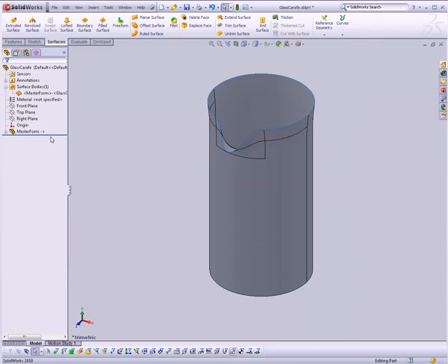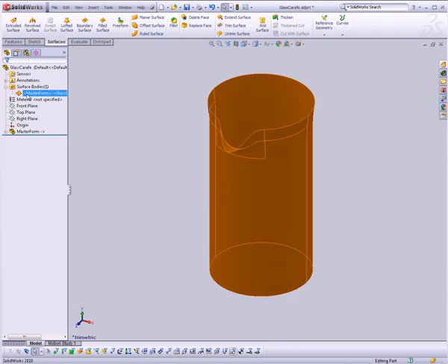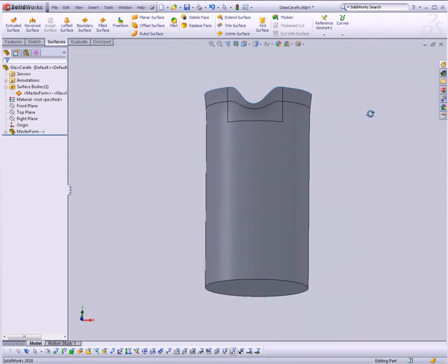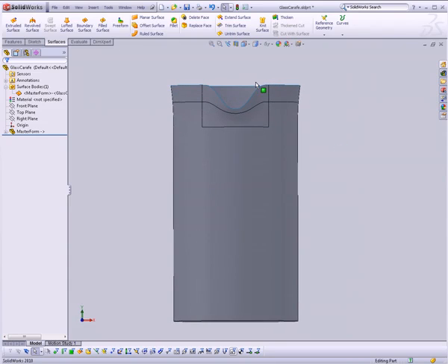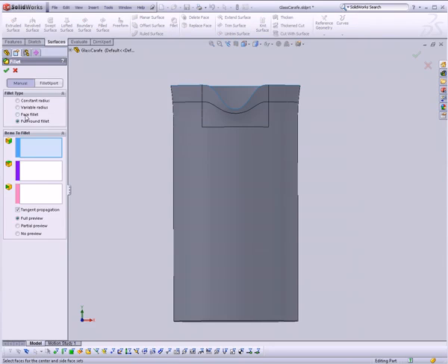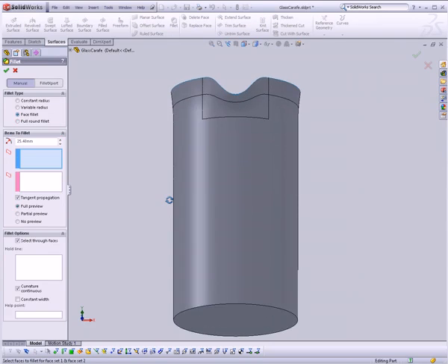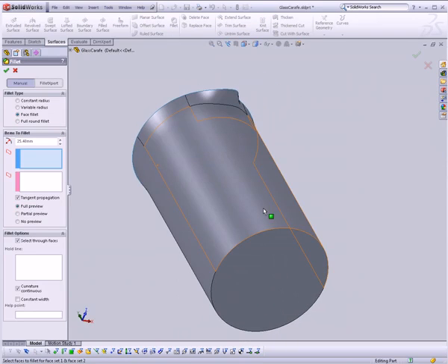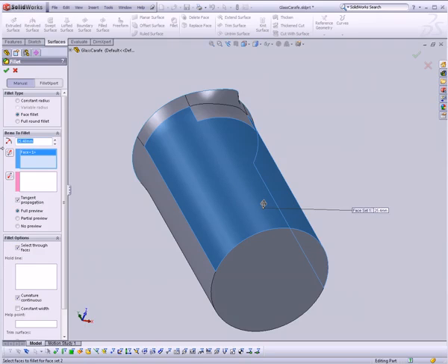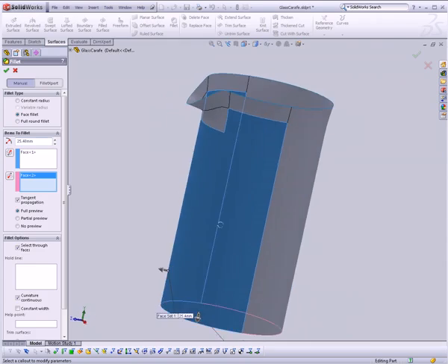So now you can see we've imported our master form and we have that surface that we created. To create the rest of the features on that surface, first I just want to add the round on the bottom. So we'll use our Fillet tool up here in the top. I'm going to choose a face fillet. Pretty nice tool. I'll choose this front face to be one side. Click on the next box and click the bottom face.